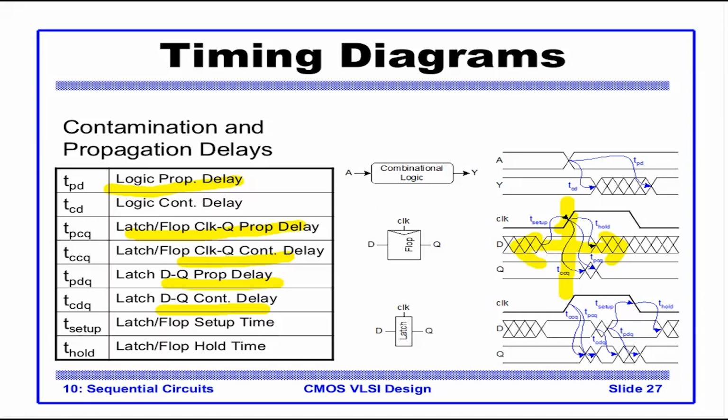This restriction is called the hold time. For a flop, the hold time and setup time are calculated from the trigger edge, that is the clock edge that triggers the event. For a latch, it is always the closing edge. That means the edge that latches D to Q, the D has to meet a setup and a hold window from that edge.